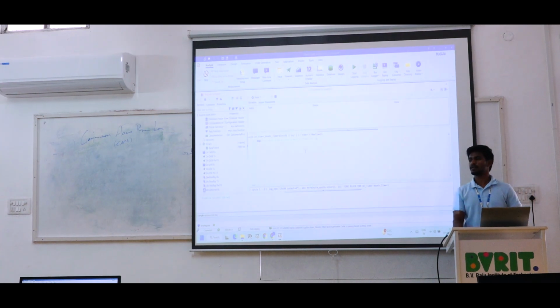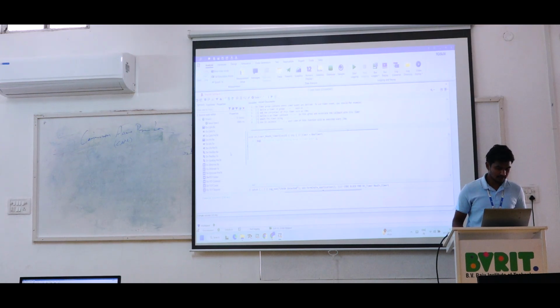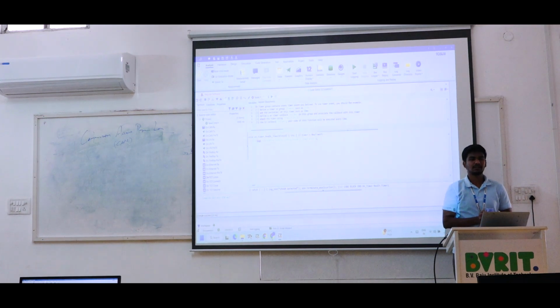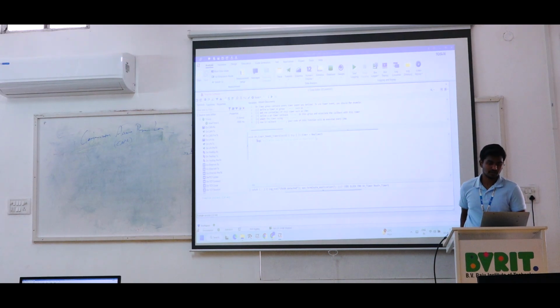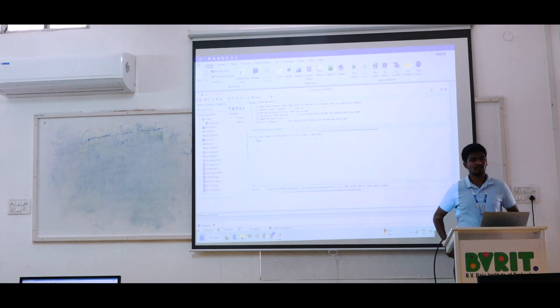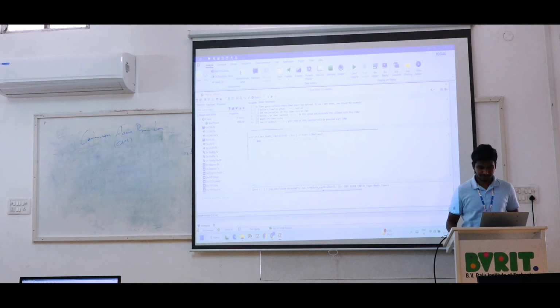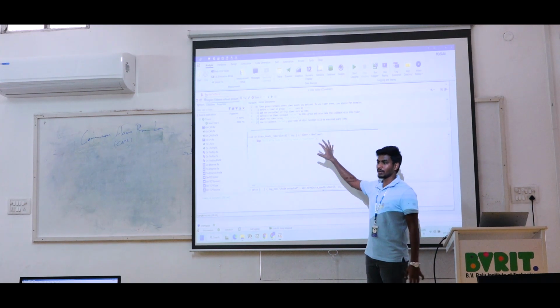Okay, so this is what we previously discussed in our last session. Now our next events are on CAN TX and then on CAN RX. On CAN RX means the messages we have received by this tool, which we are able to see here. On CAN TX means the messages we have transmitted by this tool, which we are able to see there. So that is the concept of on CAN TX and on CAN RX. For this example, you can start with on CAN RX, which means the messages received by this tool.